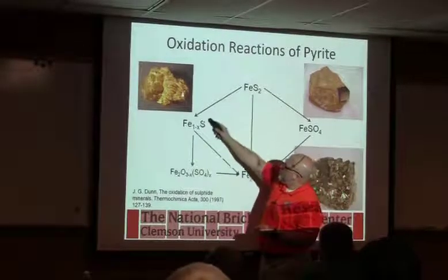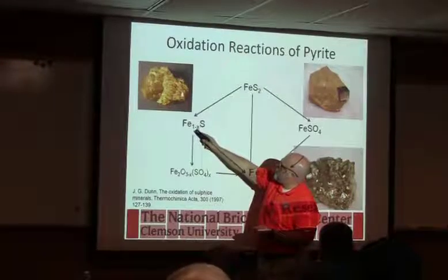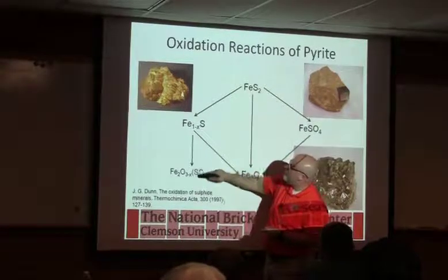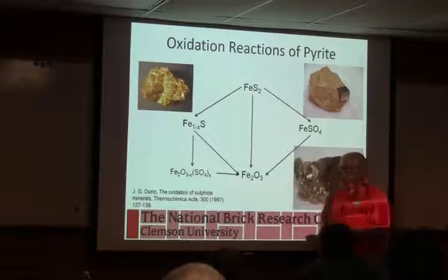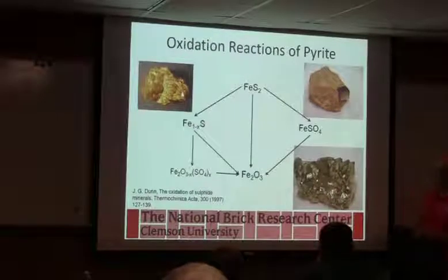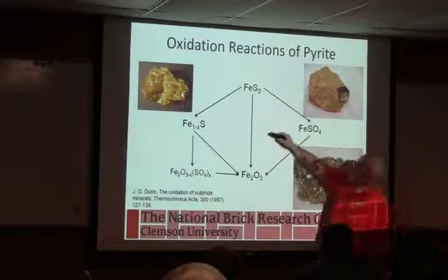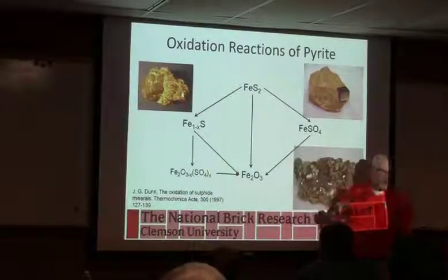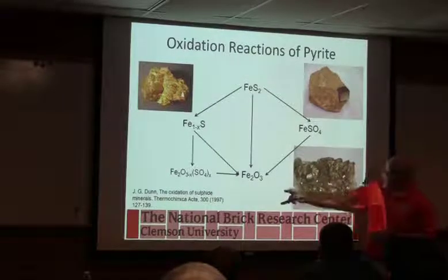If we're pretty reducing, we can actually go this direction, if there's a real deficiency of oxygen. And this stuff really causes havoc with efflorescence if we get into those kinds of compounds. So it gets really messy, and there's a lot of talk about this. And actually, the pyrite isn't stable in air. Once you dig it up and expose it to air, it starts to do this as much as it can